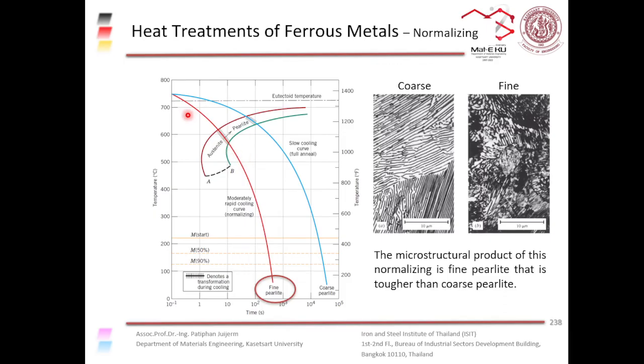Okay, so when you cool it down relatively quickly, you cool it down in air, you get finer microstructure, right? You have fine pearlite, which is tougher than coarse pearlite.